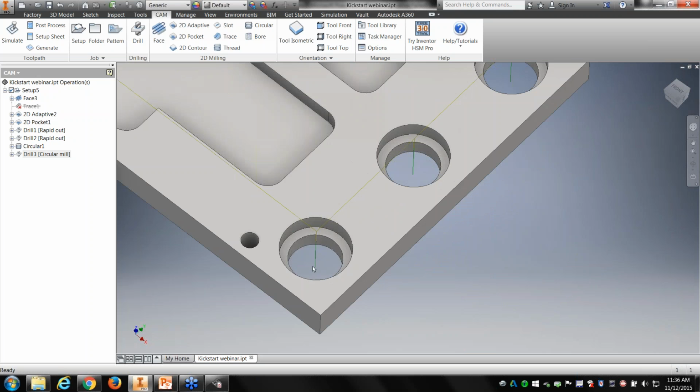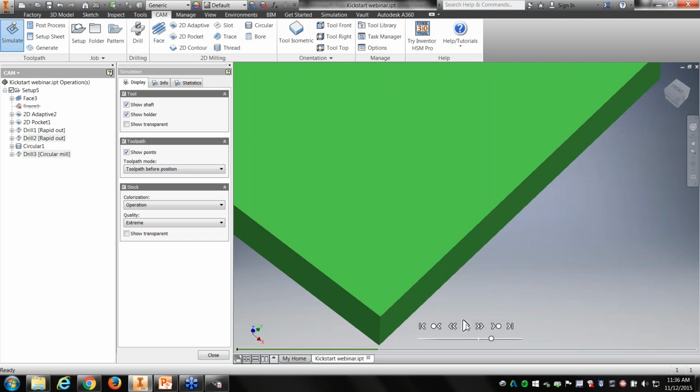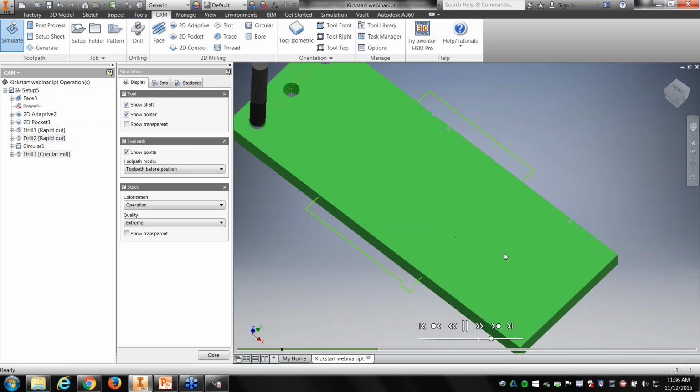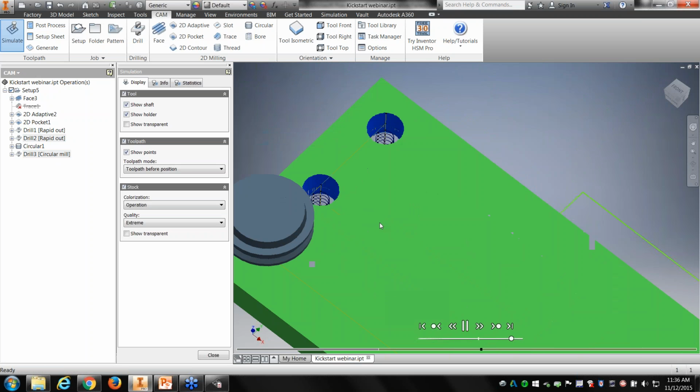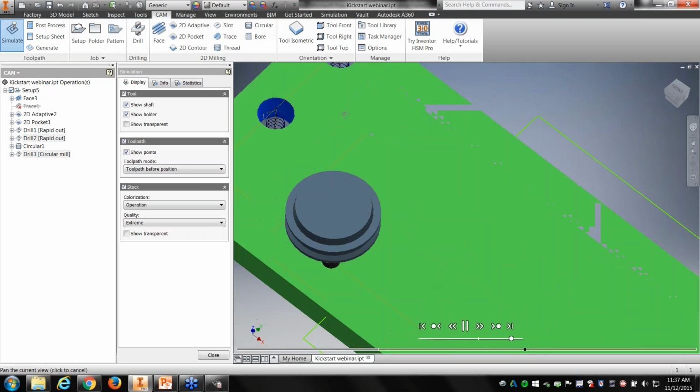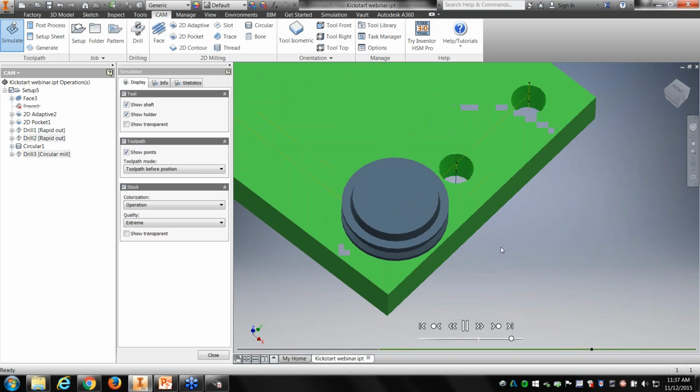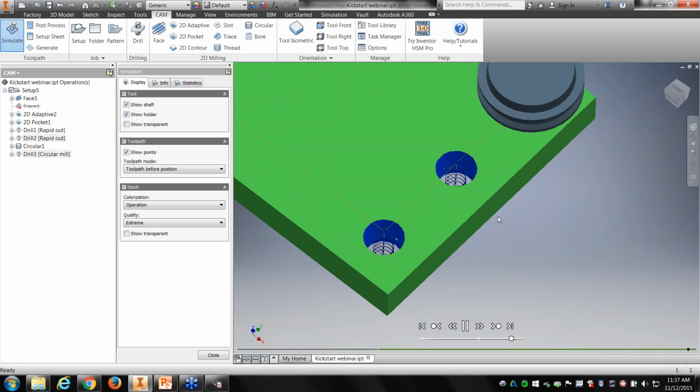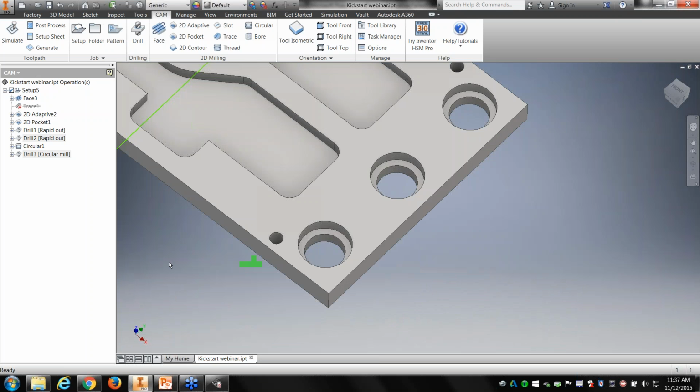And then what you see is it only shows the one depth, but if I come in here, let's do this. Let it do its drill. It actually does all the circular moves. You just don't see that in the actual toolpath outside of the simulation, but you can see it in here. So that's another way that you can go about doing circular pocket milling.